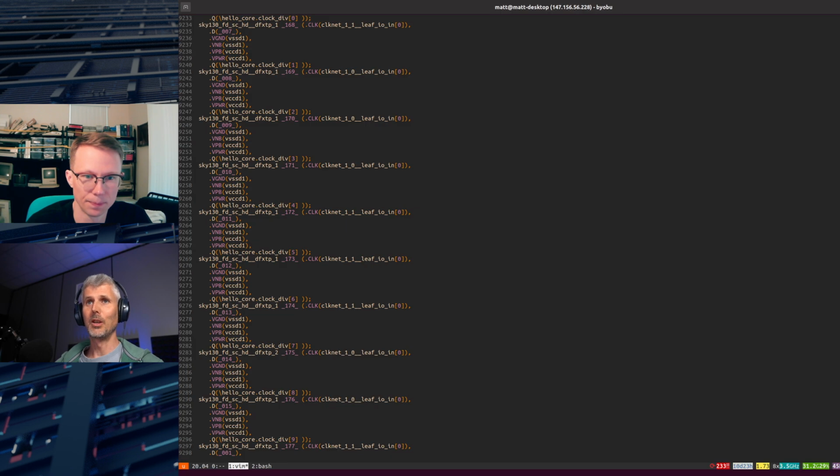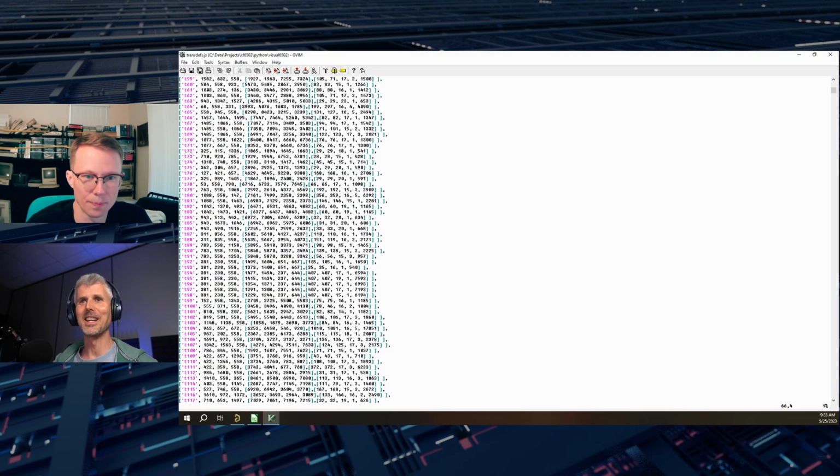And when you look at a gate level netlist, it's like a big list of not just transistors, because it's with standard cells, so it's flip flops and AND gates and OR gates, but then just wire names. So it's really impossible to read. I can't imagine being faced with that and then someone saying, "Now, can you make a PCB out of it?"